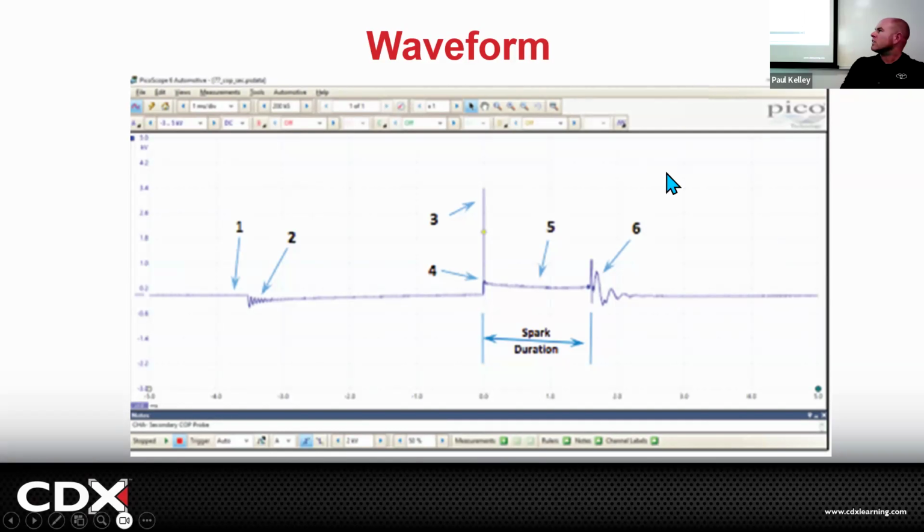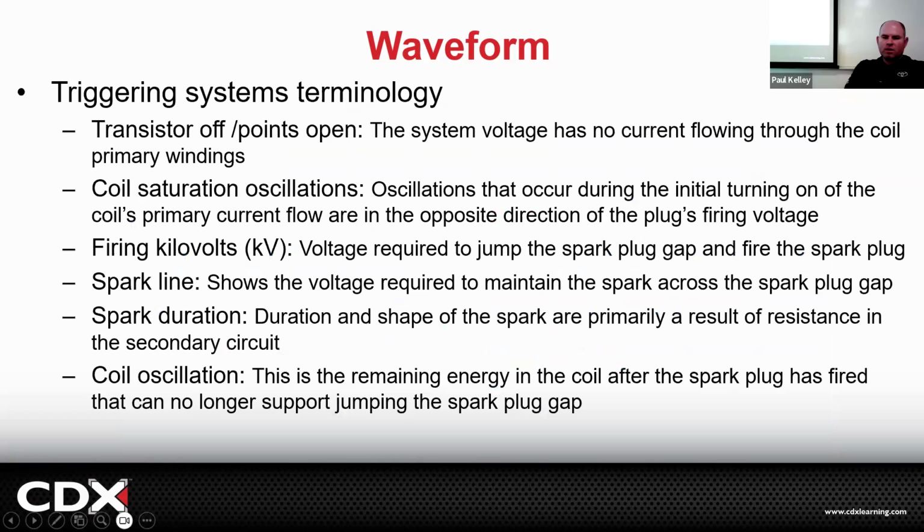And it was like, no, if it's a high firing line, that's resistance in the secondary. That's going to be like a corroded spark plug wire, a spark plug that's really fouled up and nasty, something like that, right? So a high firing line means there's electrical resistance in the secondary. Cool. Then the next one was 5.